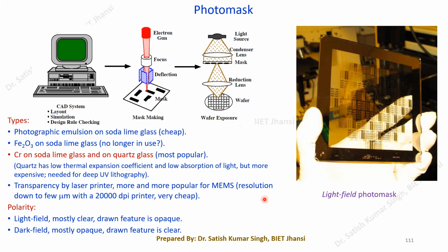Fine. Now we have to think about fabricating this one. I will explain how it can be fabricated. Before that, we have to look at one more very important factor about the mask. Whatever pattern we are printing onto the mask, this image is going to be reprinted onto your wafer. So any kind of defect available on the mask is going to be printed onto your wafers as well.